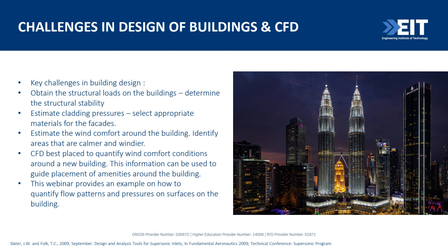And the reason they are windy is the heavily built up nature of, say, Manhattan or other places will create flows which get squeezed. As they get squeezed through buildings, they will have to accelerate, and sometimes they will accelerate and hit the ground levels from higher up, and that causes these sudden gusts of wind, which will cause a lot of comfort issues. So CFD can be used to understand and identify these issues and mitigate them.